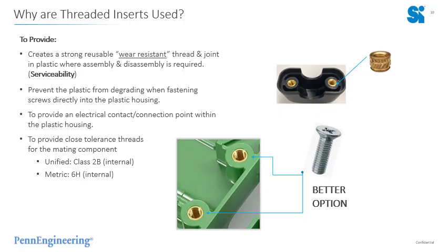You'll often see brass used in this case because of its electrical conductivity, and sometimes flanged inserts that sit on the plastic surface. And throughout our catalog, you'll see our inserts are categorized with Unified Class 2B dimensions and metric 6H dimensions.